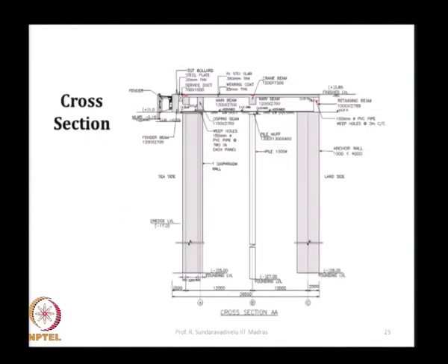Then we will go to the analysis of the structure, what has failed. Nearby there was another structure that was coming up, for which we have designed the structure. This is a diaphragm wall, this is an anchor wall, this is a pile, and we have a cross beam connecting them. There are some beams here placed and another beam here, retaining beam. There are 2 beams which are crane beams. There is a fascia beam which is used to fix the fender.